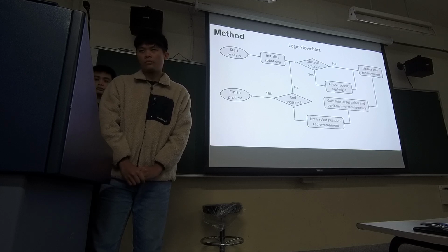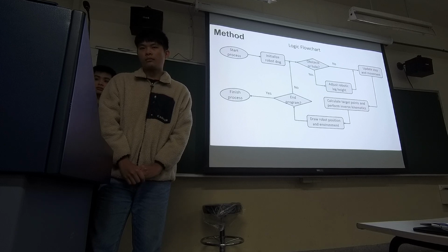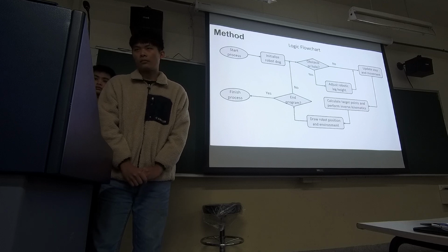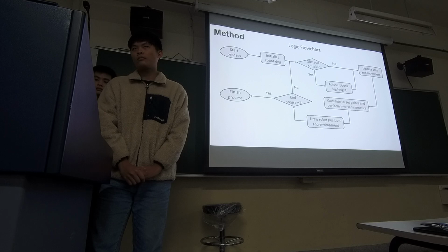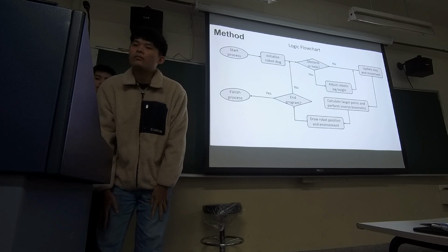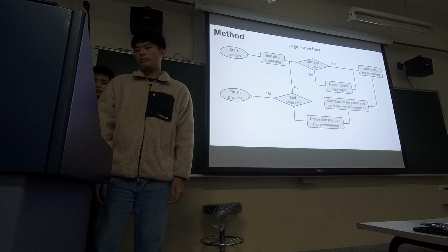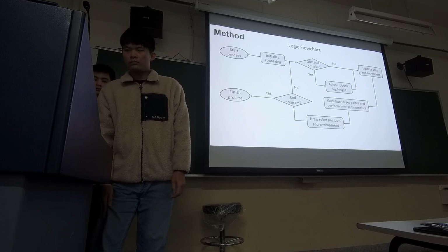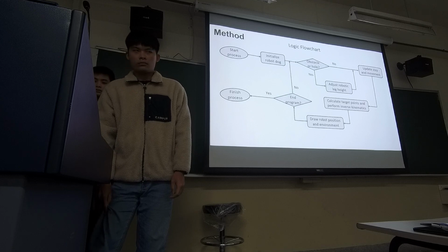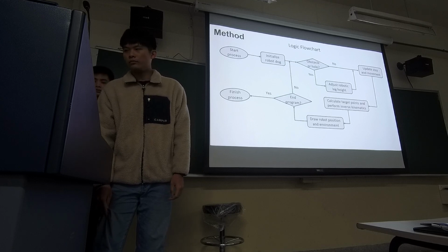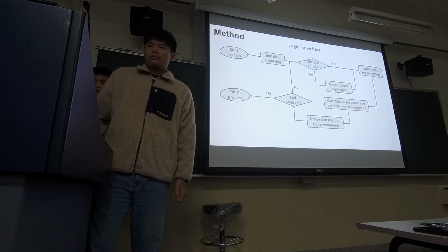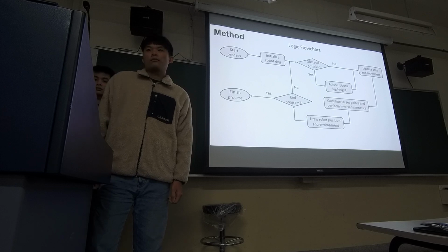Once any necessary adjustments are made, the robot calculates the target points and performs inverse kinematics. After that, the system maps the robot's position and its surroundings while updating the environmental data. And in the end, the system will consider whether the program should continue. If it needs to stop, the process will be concluded. If not, the robot will revisit to check for obstacles and adjust its movement.